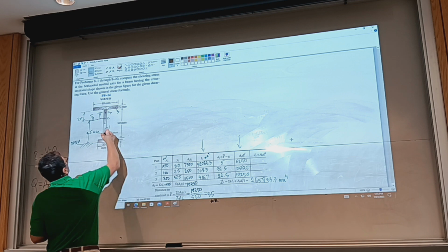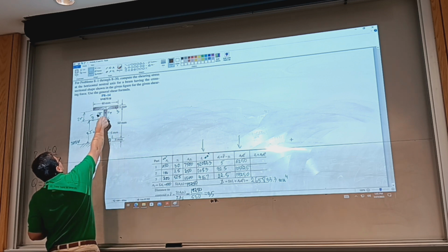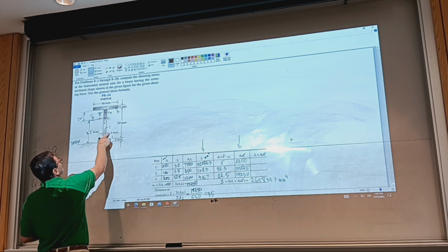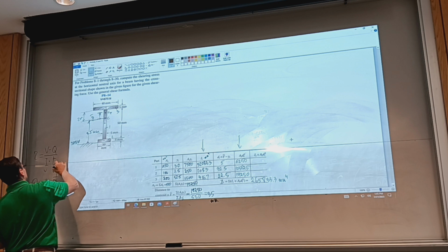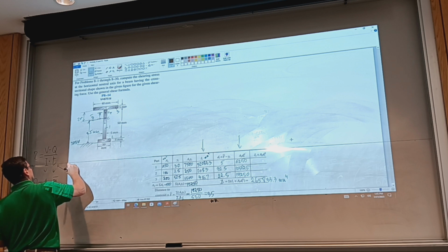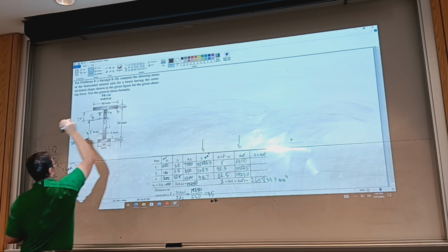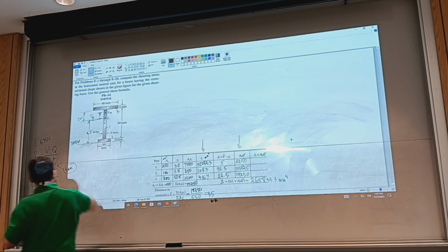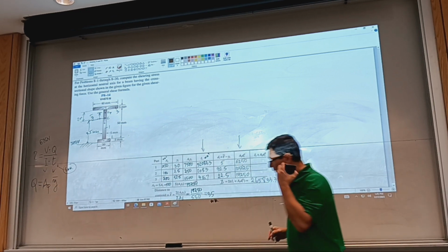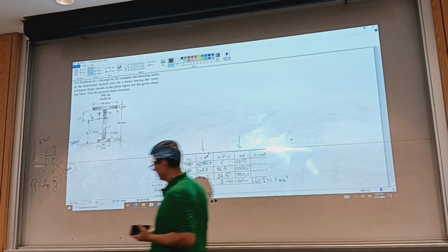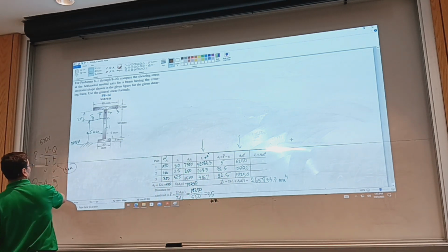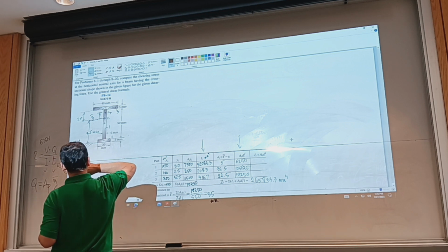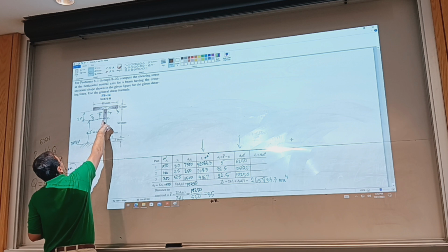Well, sometimes miracles happen. So thickness is going to be, again, we're at the centroid of the assembly, and the thickness is 5 millimeters. So we have this one, this is 5 millimeters. And then we have, given the shear force, 675 newtons, and of course we need to look at the first moment of area, the partial area. We can go with what's below the centroid, or we can convince ourselves that we get the same numbers.